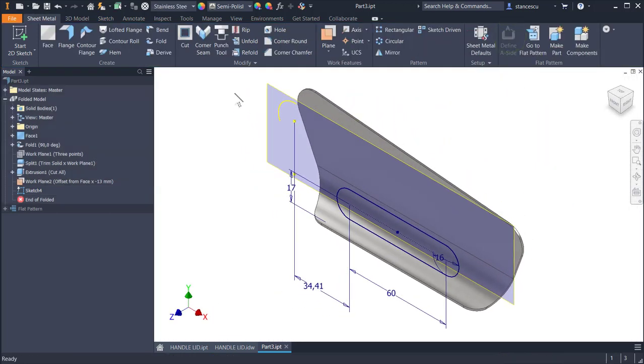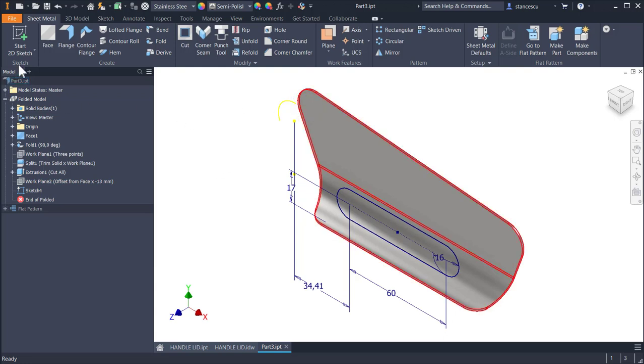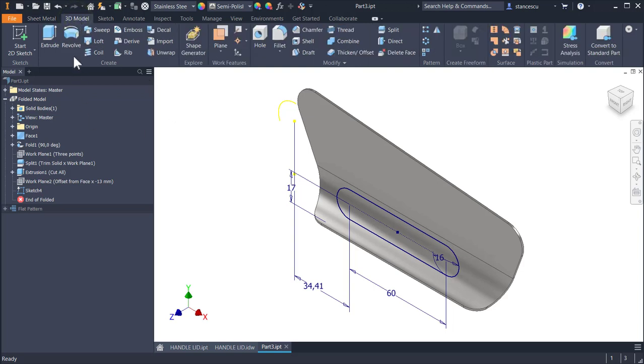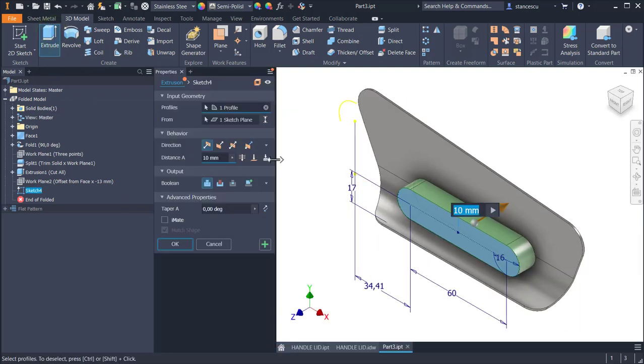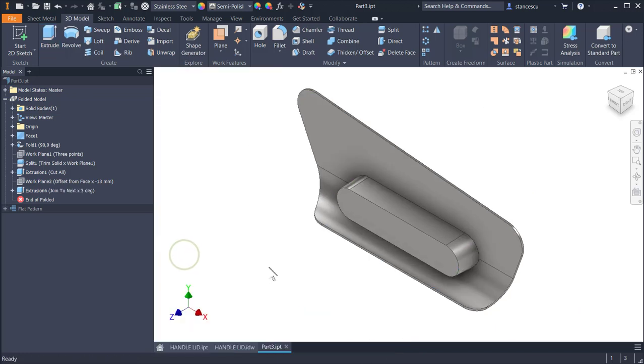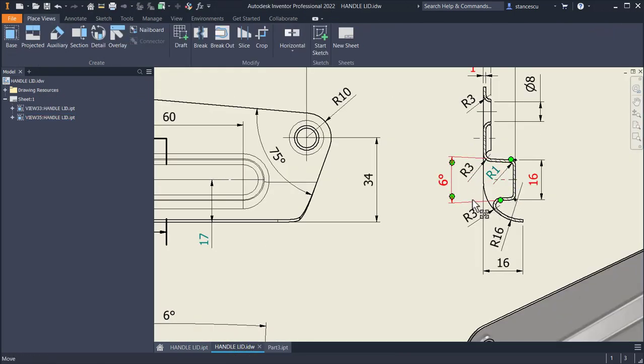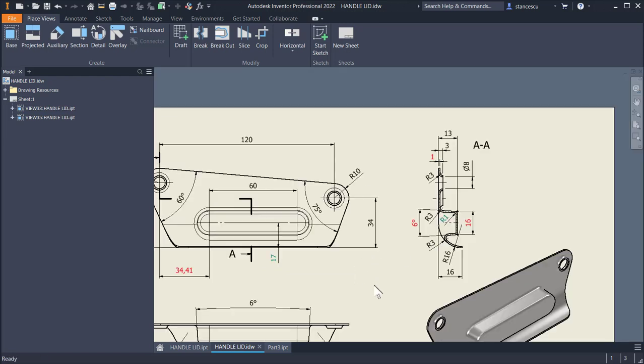Finish sketch. Hide the plane. Not project, but extrude by using 3D model environment. Extrude to the part with the 3 degrees taper angle, as you can see. Okay, the next is the void volume from inside the protrusion.